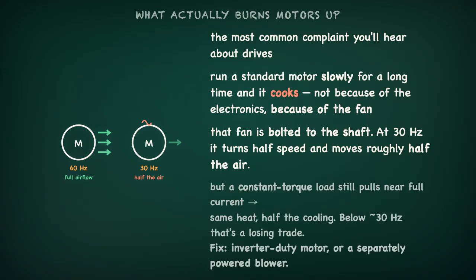But a constant torque load still pulls near full current. So the motor is making just as much heat with half the cooling. Below about 30 Hz, that's a losing trade. The fix is an inverter duty motor or a separately powered blower.